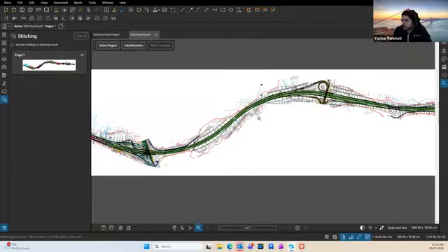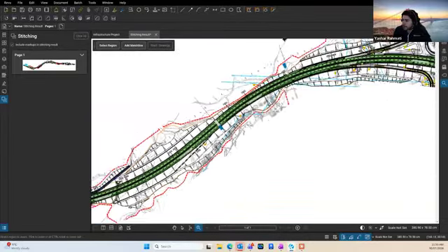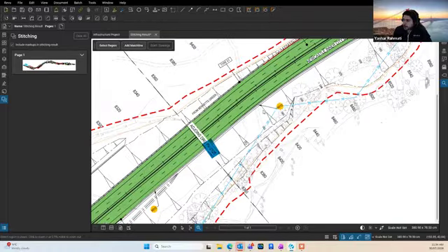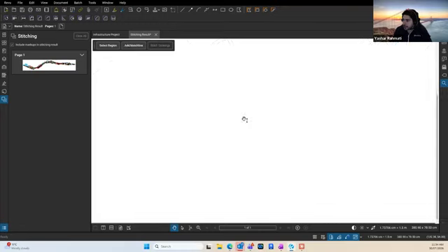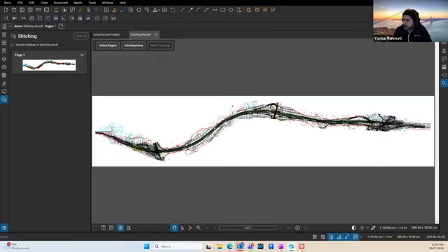And then from this point, by knowing some known dimensions on the plan, for example, I know the distance from this point to here is, let's say, 1.5, I can use the calibration to calibrate. Put 1.5, apply the scale, and now my plan has already been scaled. And from this point onward, I can start measuring the full length of this road, or start adding markup and also save this file as a separate document.